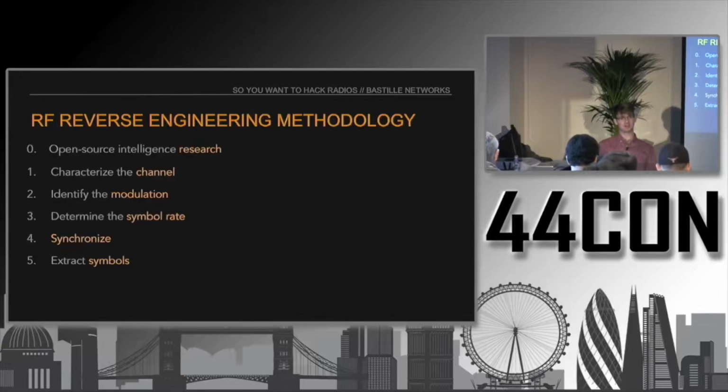And since it's a constant frequency, there's no frequency modulation happening. We don't have to worry about that. So at this point, we've characterized the channel. We've identified the modulation because visually we were able to look at the spectrum and see that what was being modulated was the amplitude. That's the power of the signal rather than the frequency.